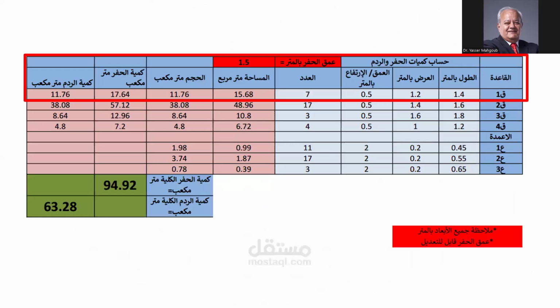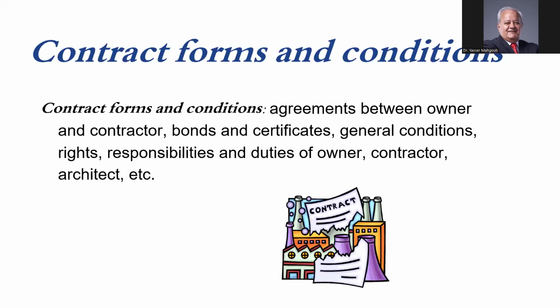They also have to provide for each foundation the size, the quantity, the quantity of concrete, the quantity of excavation, and the quantity of refilling, and this will be used for the bills of quantities. So each specialization will give you details of their work.